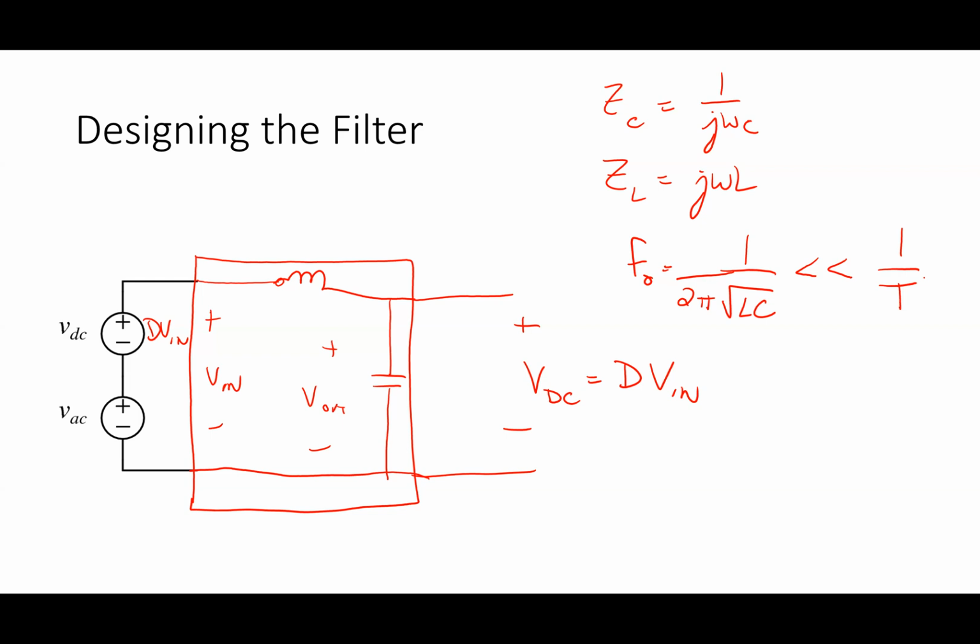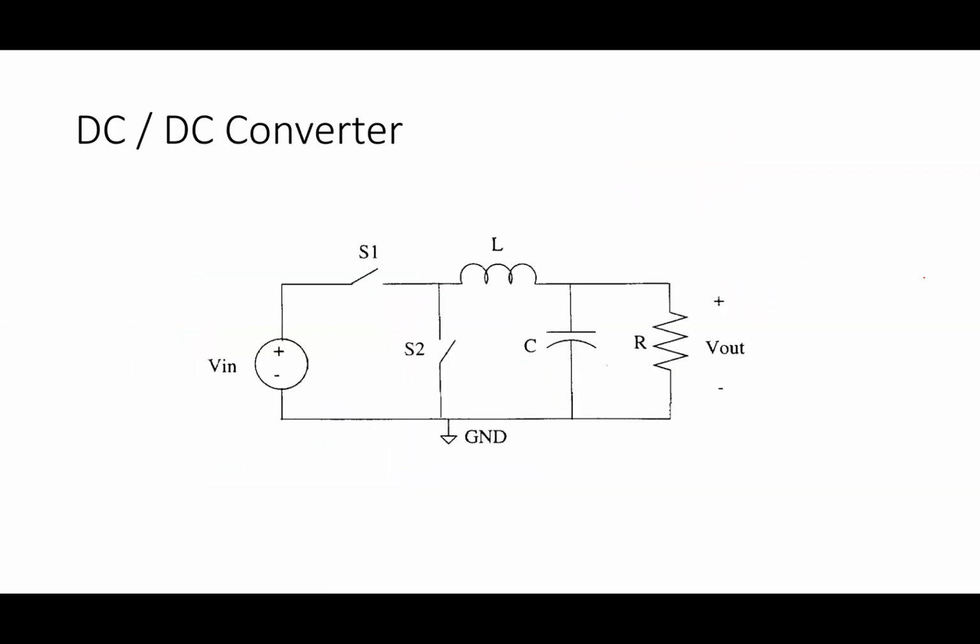If I do that and set that up right, then what that leads to is my basic DC to DC converter. This guy here is called a buck converter. If you start learning DC converters, start doing power electronics, there's all kinds of converters. It's another sort of Forrest Gump list of different kinds of shrimp, a whole bunch of them. Basically, this buck converter is what I call a down converter.